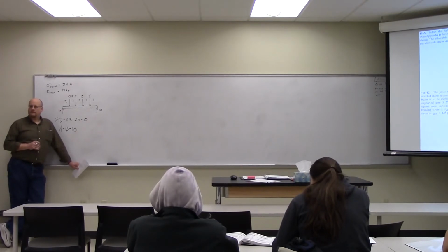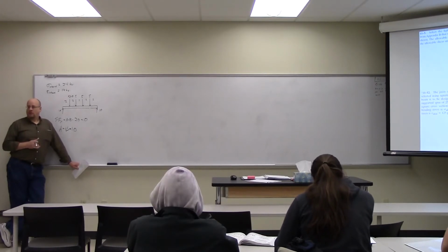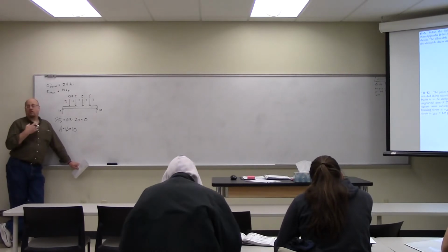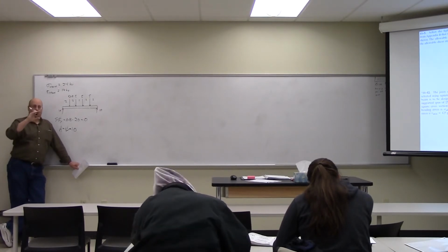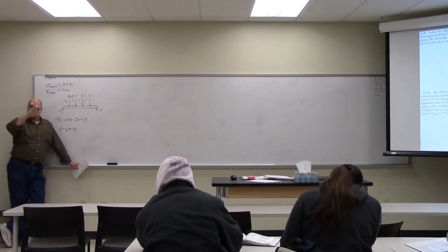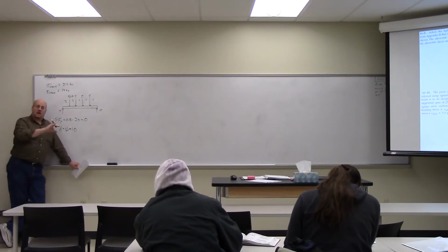Well, that's always greater, right? Not always greater, but it's usually, what's that? Yeah, it's driven by the fact that beams are usually fairly long. So the bending moments are typically greater than the shear forces. Right? The bending loads typically have a greater impact than the shear loads. And so we're going to start there. So remember the process is check for the normal stress due to the bending moment first. Design around that, and then confirm at the end that your shear load is being borne without failure. Everybody with me on that?